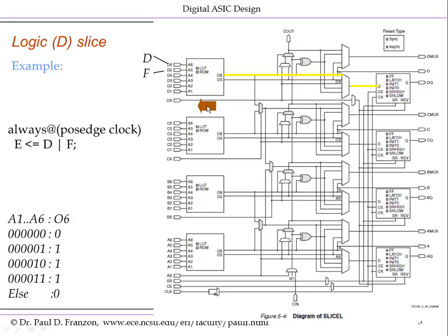Then we have the steering logic that is set by external SRAMs that are not shown, going to the storage element, which in this case will be configured as a flip-flop, again by storage elements that are not shown. So this is a simple example of how the compilation tools will map RTL onto a piece of FPGA technology.